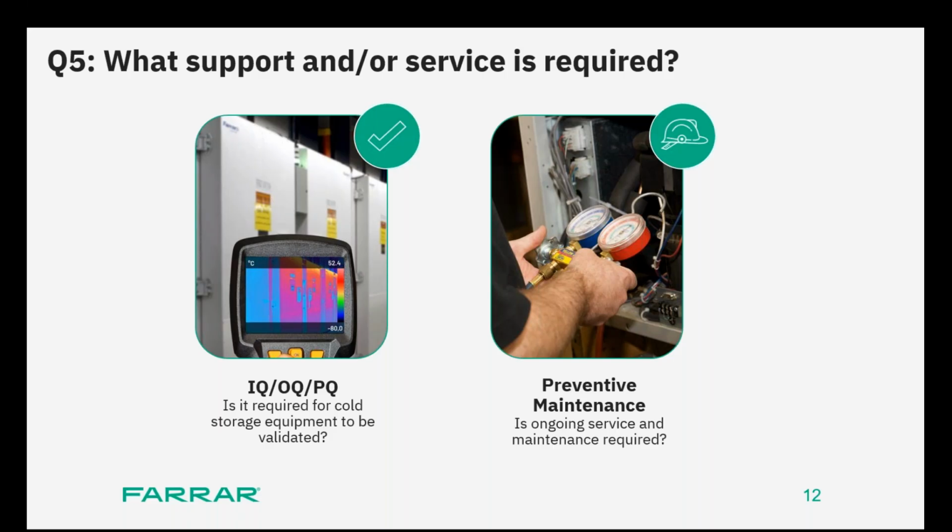So when you're looking at the validation aspect, you have IQs, OQs, PQs. So your IQ is an installation qualification. So we're going to show you that our chamber is doing what we said it was going to do. It's relatively defined. Your temperature and uniformity is wide open, showing you what's going to occur with it, and it's mapped out. Then you get into your OQ, which is an operation qualification, and we're going to verify that your equipment is designed properly, and we're going to prove that to you as well.